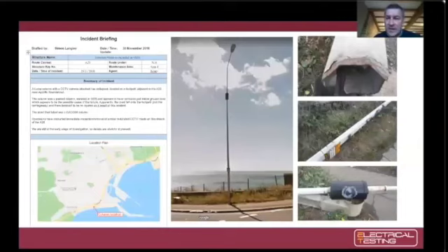We're quite fortunate in the industry where we see safety alerts, and they enable us to identify problems, and we obviously act accordingly as an industry. When we see safety alerts for column failures, there's often a link with an attachment that's being supported by the column. This one came through a couple of years ago. It's a column that's 23 years old. It's a folded sheet steel column. It's coastal located, so it's obviously exposed to high winds, it's exposed to sea and salt air, but it also houses a CCTV attachment to it as well, and that was a contributing factor.